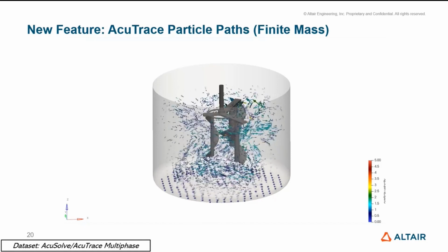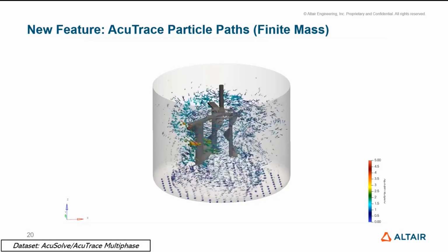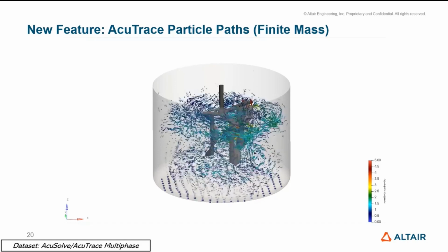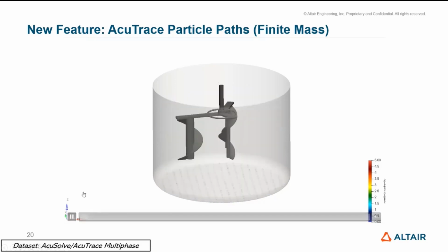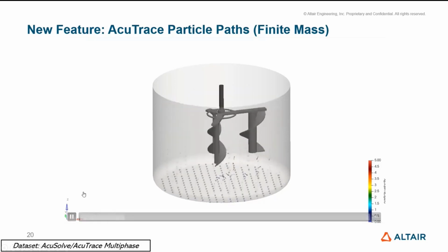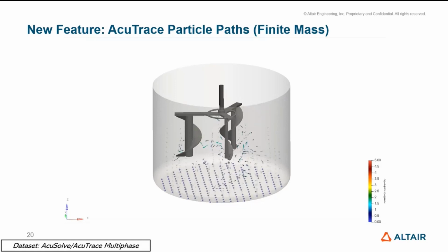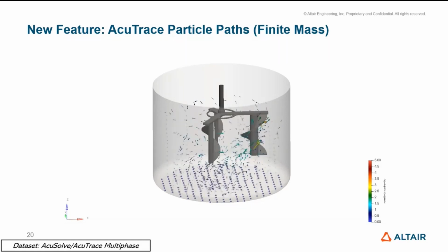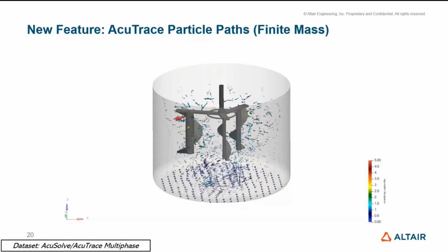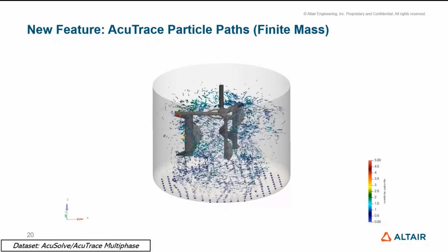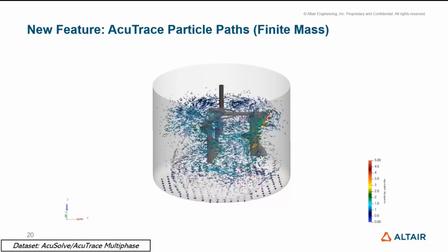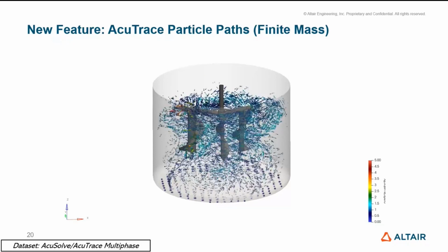And then we can color those particles by velocity magnitude and then also add the vector scaling based on magnitude. So I kind of like this simulation and the result that we're able to review here because it does give you an indication of where you have those high rotations in the flow. And then I think it does highlight pretty nicely how the particles actually move within this flow field as opposed to just showing the particles alone.